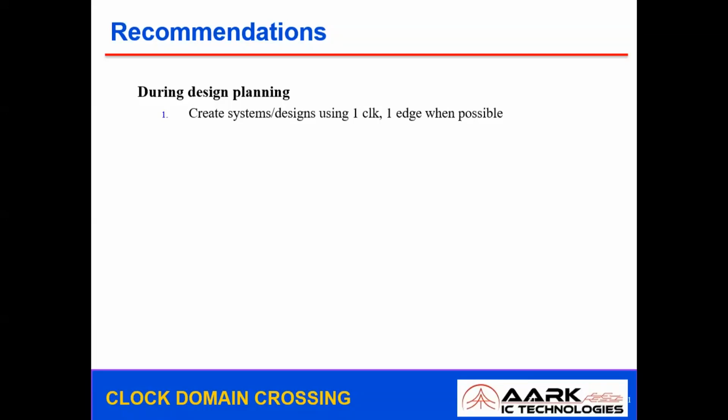But when you add a FIFO, it adds a lot of additional logic. So if you can overcome this issue with a two-stage synchronizer, it is well and good. And if it is a critical issue, for example, if one block is operating at 10 kilohertz and the other one is operating at 10 gigahertz, then these two-stage synchronizers might not help. Therefore, we should go with the complete FIFO design, which needs to be calculated with the FIFO depth. Based on your write frequency and read frequency, we consider the memory that is required to store this data. The write side writes the data, and the read side might operate at a different clock and read at a different frequency from the same memory location.